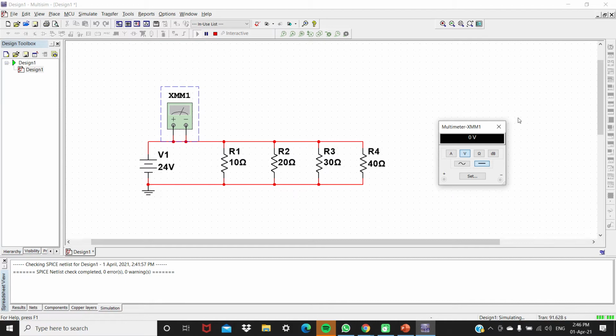If you have 2 points with the same potential, be it 500,000 volts or whatever, the current is not going to flow, because there's no difference in potential. This is the exact classic example when we as engineers work at high voltage level. It's called lifeline.